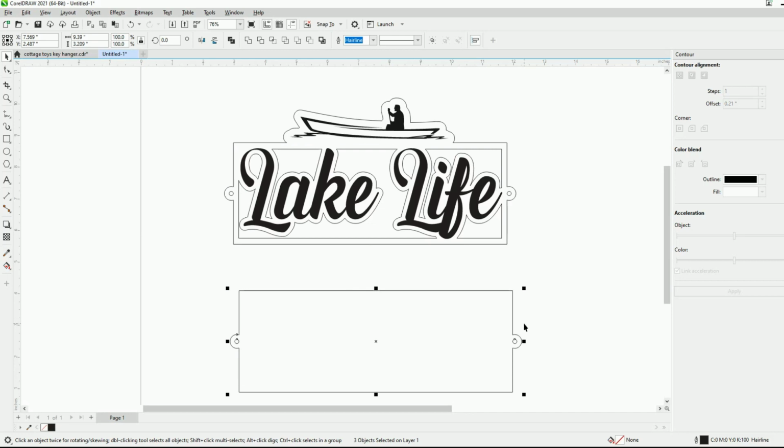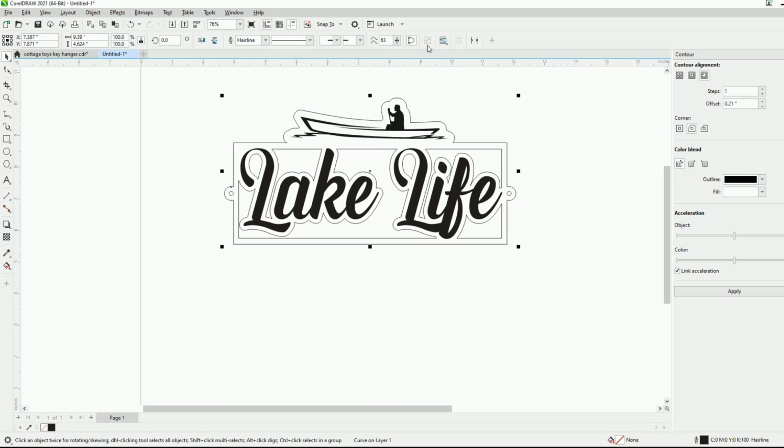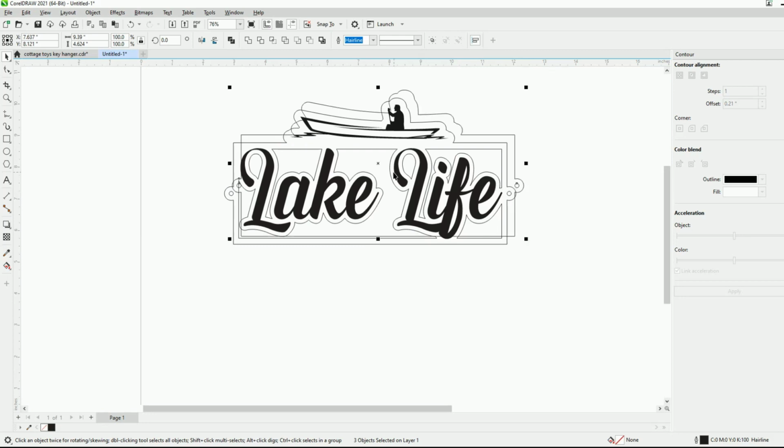So let's get rid of that second layer, and we're going to select our original frame and duplicate it, or control copy, copy paste. Oh, wait a second, I forgot to add something. I forgot to add those little pilot holes. Remember these little guys? So we're going to hold our shift key down and drag our selector over top of those two little donut holes, and then duplicate so we make sure we've got those pilot holes in the second layer as well.